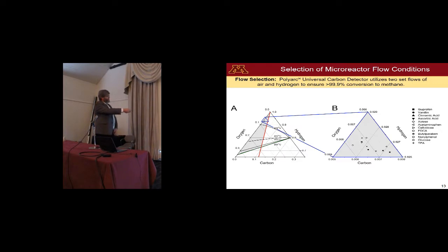There's another line I need, which is the combustion line. So if you're to the left of that, you have enough oxygen that you'll achieve complete combustion in the first chamber. So there's a nice design optimization problem. I want very high temperatures for favorable kinetics, but as my lines slip up here, I get less space where I can achieve my selectivity metrics.